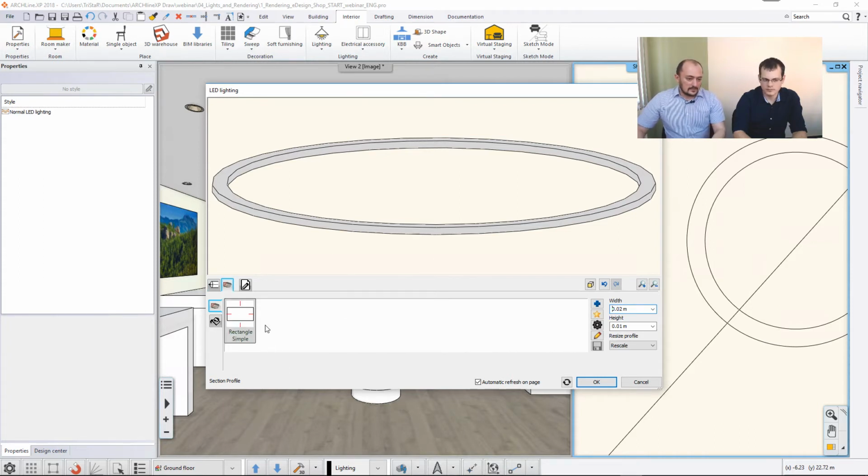This is a rectangular cross-section profile, but again I can go to the libraries and even design my own and use it. It's the standard sweep command. It works the same with the decorative elements or the pipes that you want to put in. You have to define the path and you define a cross-section. Yeah, if you saw one of our decoration videos, that's the same thing. It works in a quite similar fashion.